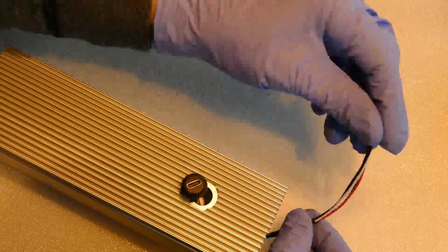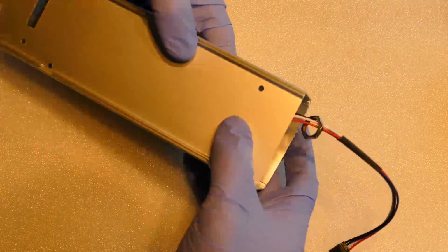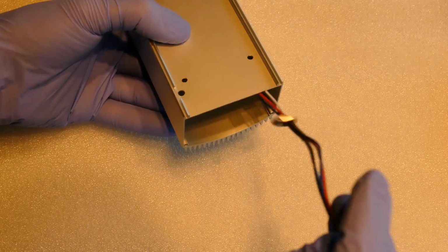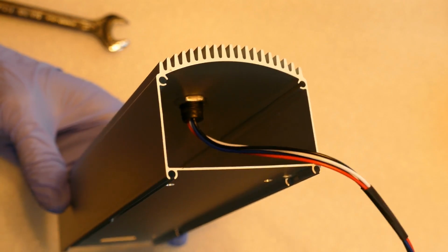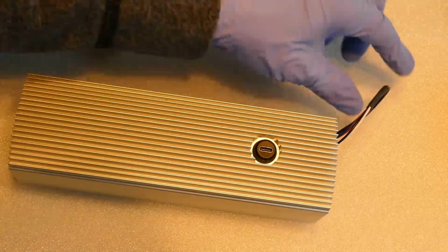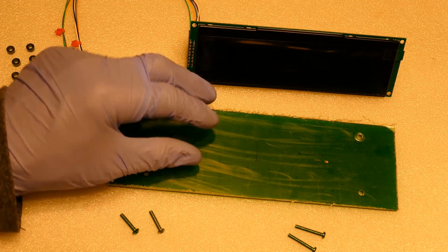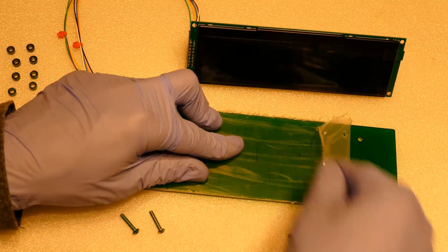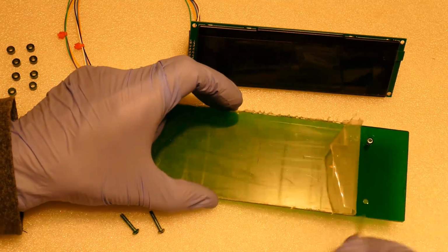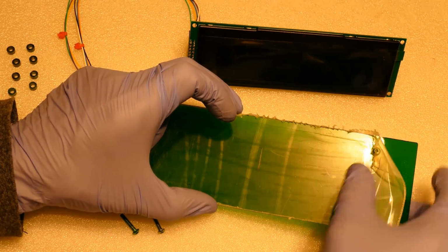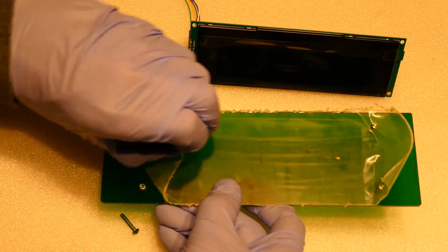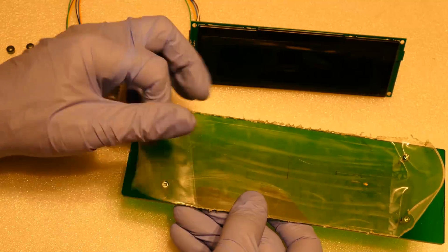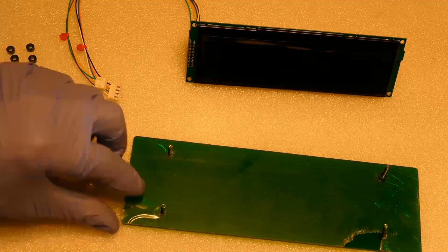In future projects, I would just buy a very short USB-C extension cable and either 3D print or CNC a panel mount for it. Alternatively, I could have just run a USB cable out the back with a strain relief grommet. I'll peel back the protective plastic on the plexiglass cover so I can insert the screws. I'm using M3 x 20mm green anodized aluminum socket cap screws. Folding the plastic back will hold the screws in place while I assemble the device.